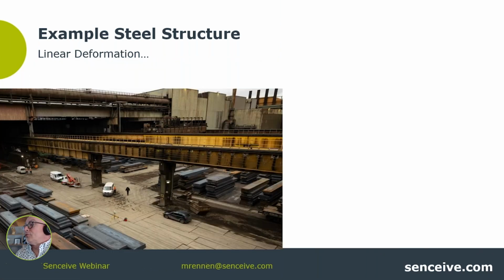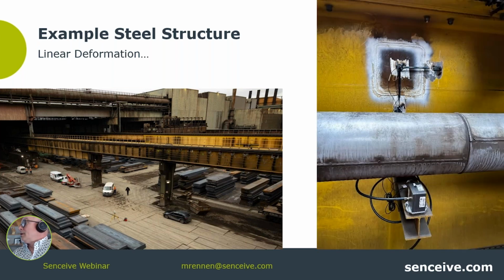And then, of course, this is the beam. They are pretty large and you could walk inside the beam. And then we knew that there were several areas where we already had cracks, and at these areas there were patches already; here is such a steel patch for a crack. We have two-dimensional crack sensors installed to measure the deformation.